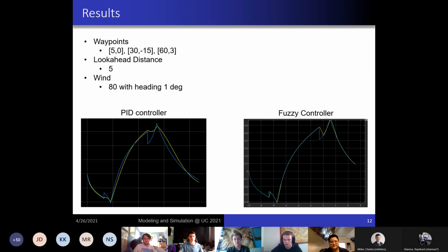It has much quicker rise times, settling time, and very little overshoot. The PID controller, by the way, was tuned somewhat roughly. Better tuning could be used, which would get somewhat better results, but from a quick tune, this was about the best we were getting.